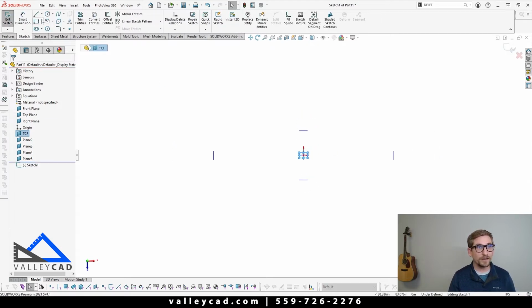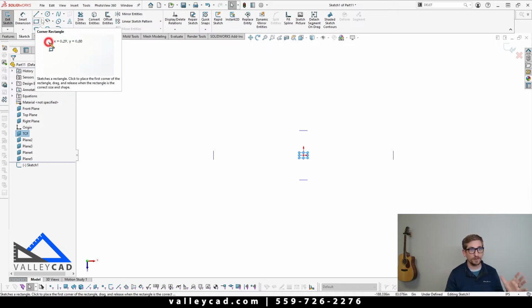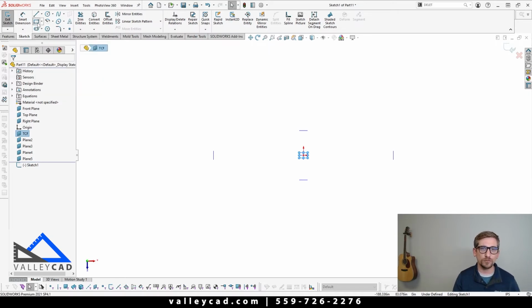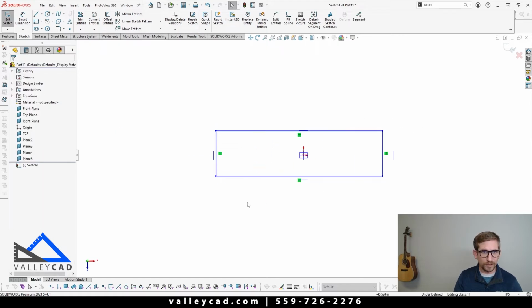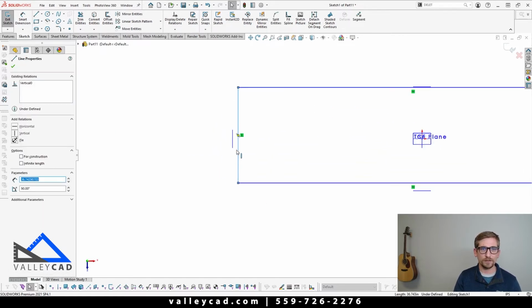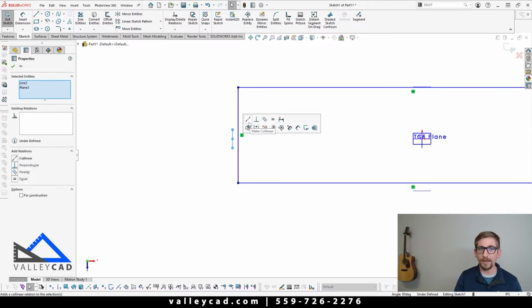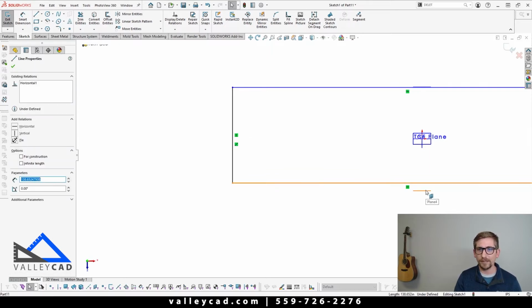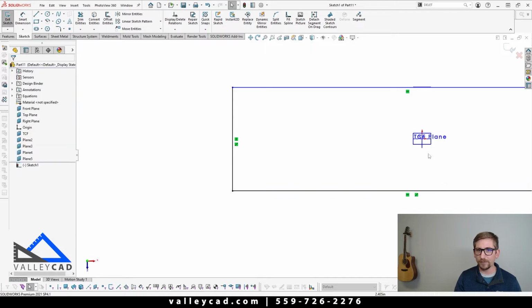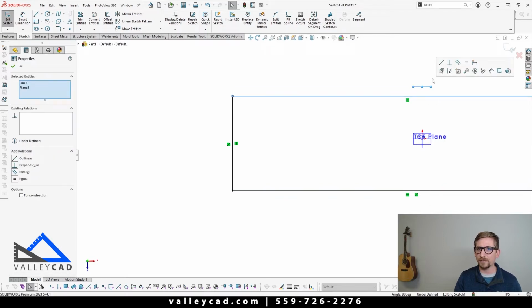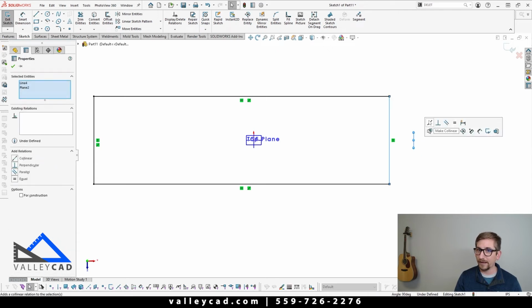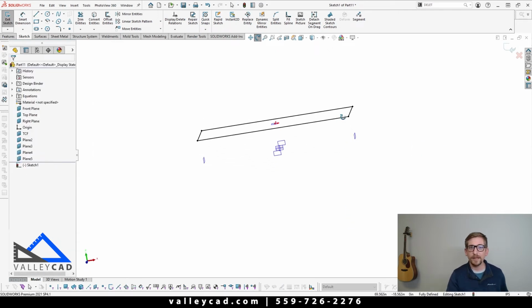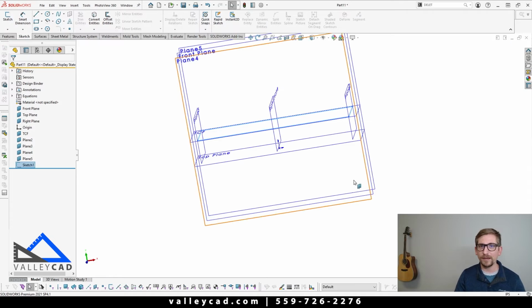So in this scenario, I'm going to select on that top of conveyor frame and create a new sketch. From here, I'm going to utilize my existing reference planes to control the size of my rectangle here. So coming in from here, I'm going to select that line, select that plane, and say, hey, be collinear. From that plane and line, make that collinear, and then also do that here, say be collinear, and then do that again over here. Make that so it's collinear as well. Now from here, I could simply say okay to that.